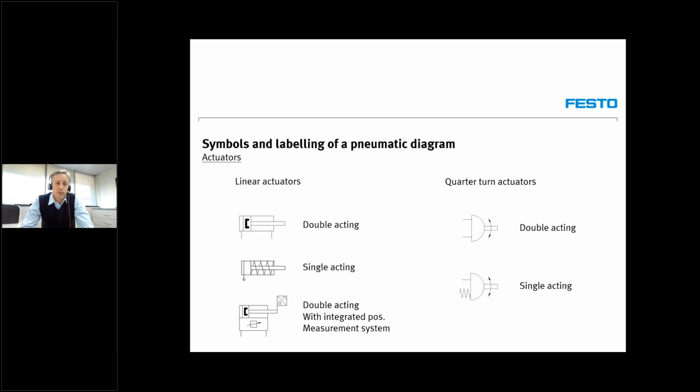But like I said, one way to determine it is to put the differential pressure gauge over the supply and the output line. Whenever the differential pressure increases, you will know that your filter is blocked, and it will give you a good indication of how often you'll have to replace that filter element.